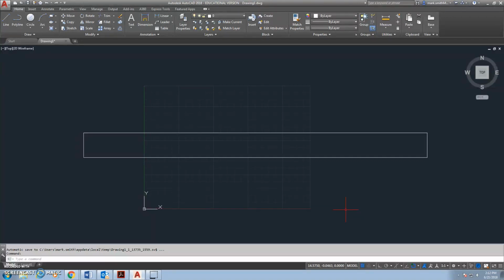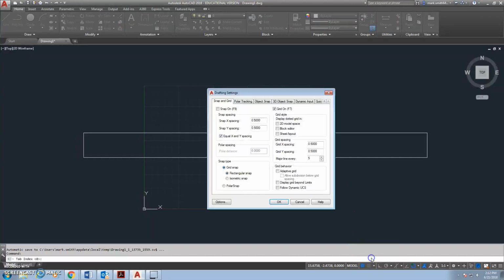And when students are just learning how to use AutoCAD, one of the tasks they have to do is set up an electronic environment. Having the grid displayed beyond limits turned off alerts the student immediately that something isn't right in their setup, because their rectangle that is created the right size is bigger than the electronic environment, so they need to change something there. Or they can check and see, is my rectangle the correct size? Maybe it's not, because my limits are showing me something isn't right. So it jogs their memory right away that maybe I haven't done something correctly.